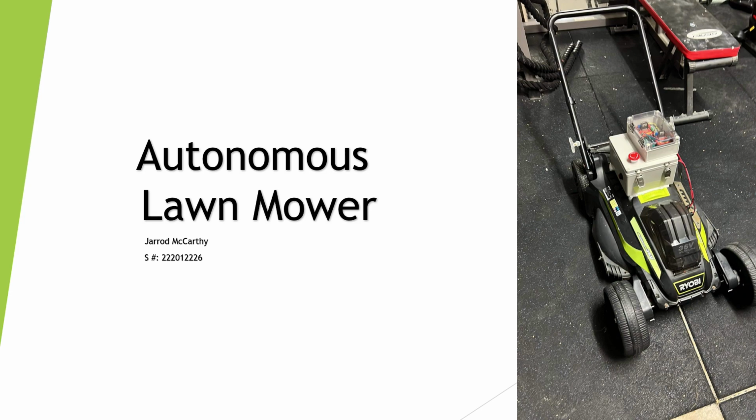And if there's some local disturbance in the map, like a person or an animal gets in the way, a camera picks up and does object detection on that person locally, and the nav stack picks up there's a person in the way, and the mower does obstacle avoidance around that person and continues mowing the actual map. So that's sort of the use case, right?